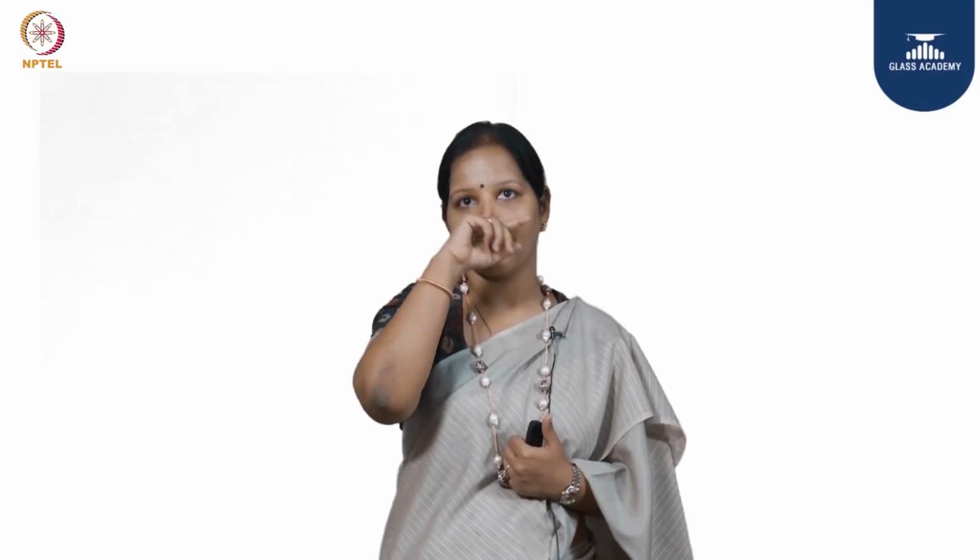Similarly, in this orphanage we made sure that the evening time spaces, where you do not need maximum daylight, are located in the central part, and of course east and west were masked by toilets and your core areas, your service areas. And if you see the depth of the floor plate, we did not increase it too much, especially for the critical spaces, so that there is enough daylight.